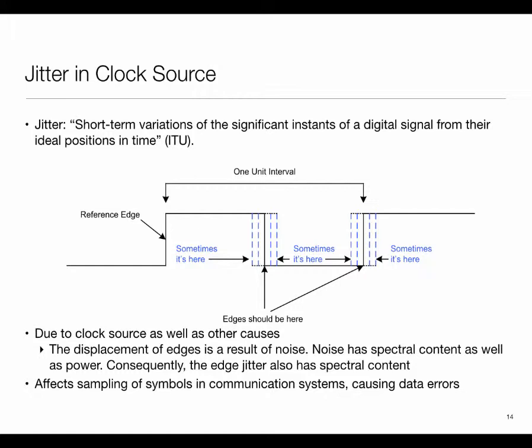Protocols or interfaces where you might think I have finer control, like if you look at the SPI bus, a very simple serial bus, even there things may matter. So I was talking with someone and these guys were trying to do very fine time synchronization. Their processor talks to their radio using a SPI bus, which is, as I said, a very simple bus, a data line in each direction and a clock line. And they were seeing roughly half a microsecond of jitter in their timing. Okay, you might say big deal, but these guys were trying to synchronize things down to 0.1 microsecond. So half a microsecond is a big deal then.